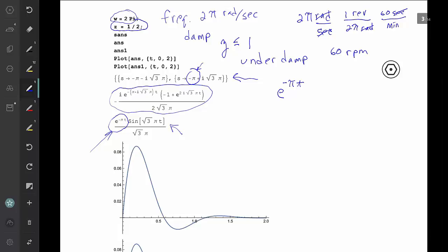Okay, so is it stable? Yes. Why? Because the real part happens to have a negative number. And so here, in the solution, you have E to the negative number T, which means that as time gets bigger, this term that's circled here will get smaller and smaller. So yes, this guy is stable. You get that from the real part.